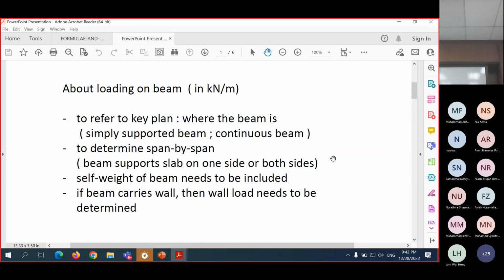In your design project, we do not expect you to calculate, for example, how much the lapping is. But just take note that in actual design, lapping is necessary. And the lapping must follow certain lap lengths to make sure that the stresses can transfer from one side to the other. So there are requirements for lap length.